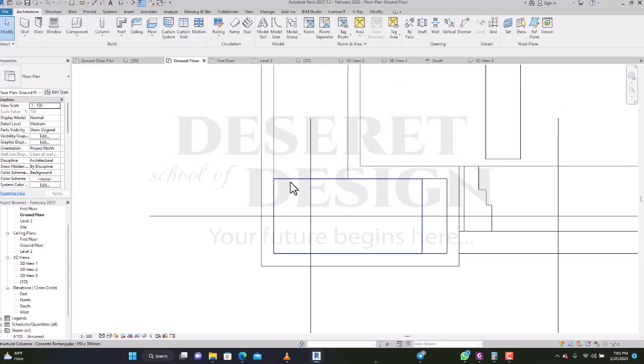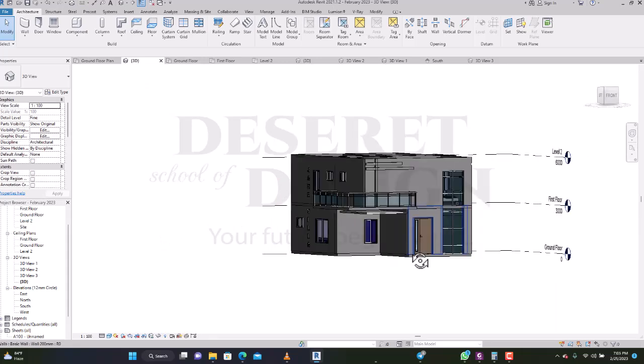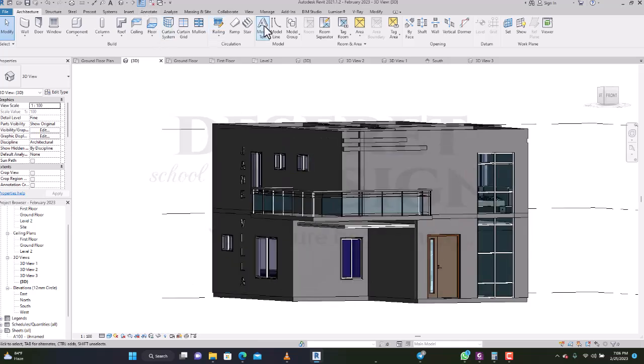That's why the detail level is set to medium for us to see our layers. So we flush it with the wall rather than the plastering. The moment you flush it with the plastering, if you come to your 3D, you'll be seeing the column on the surface of your wall. Do you get it? Yes. Okay. So nice and easy.